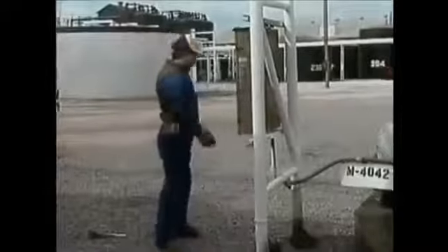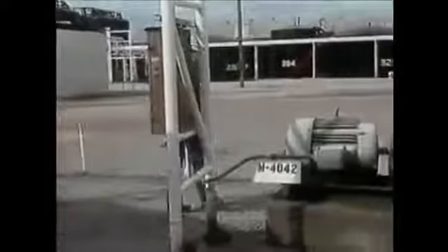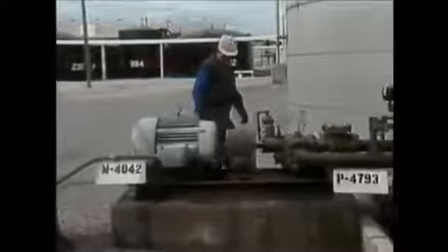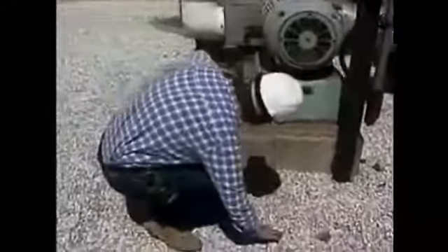Once a motor has been started, it's important to make some operating checks to ensure that the motor operates properly. Operating checks are a vital part of keeping process operations running smoothly. By making these types of checks periodically, an operator may spot potential problems before they become serious. Typically, operators routinely check for proper lubrication, excessive or unusual noise, and excessive heat or vibration. Proper lubrication is an essential part of good motor operation.